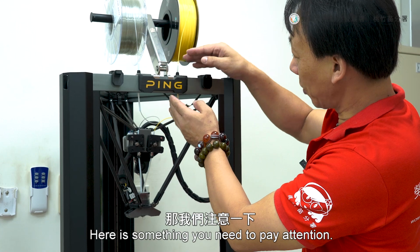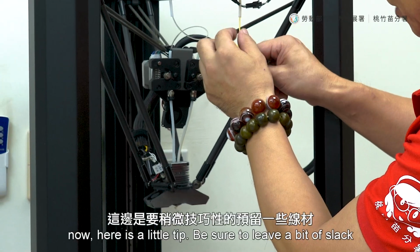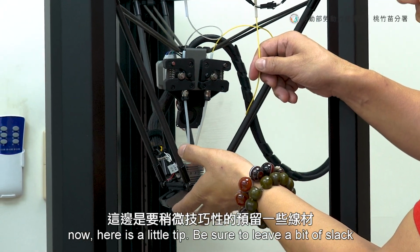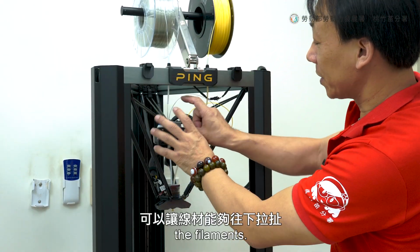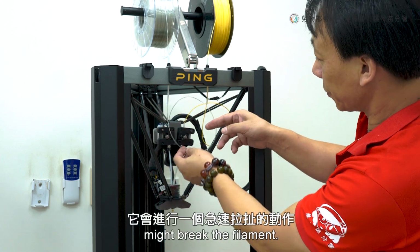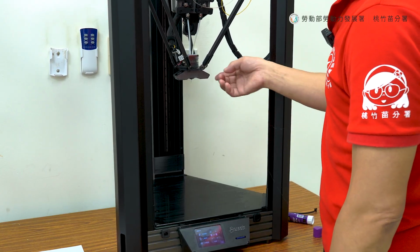Here is something you need to pay attention to. Between the first and second tube, here is a little tip. Be sure to leave a bit of slack between the tubes to allow the nozzle to move downward without stretching the filament. If it's too short, the pulling down action might break the filament.